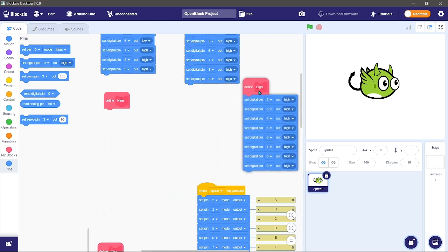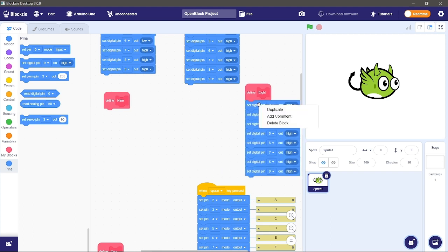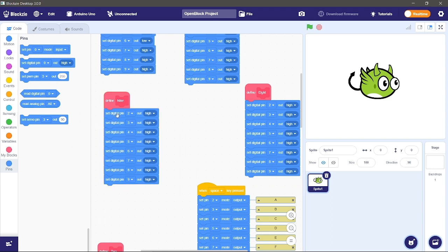And to print 9, the only pin which is going to be low is pin number 6. So by turning off pin number 6, for a few seconds, you will have the digit 9 on the screen, and this is how you can print on the 7 segment display from 0 to 9.